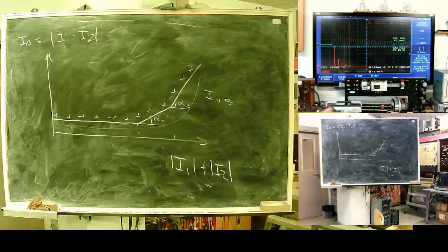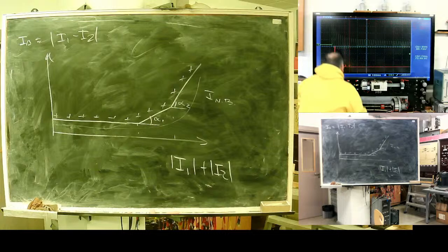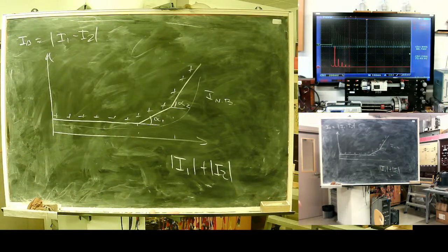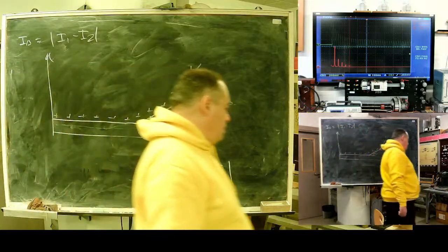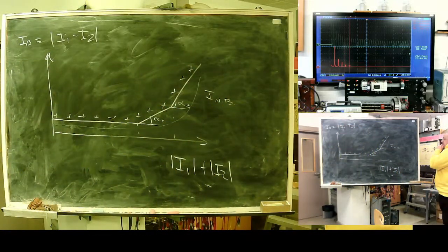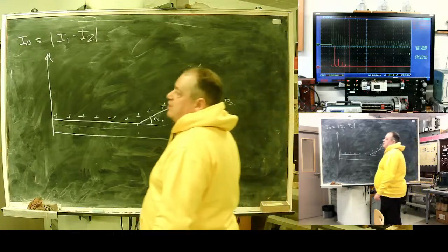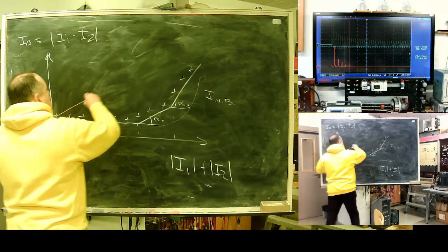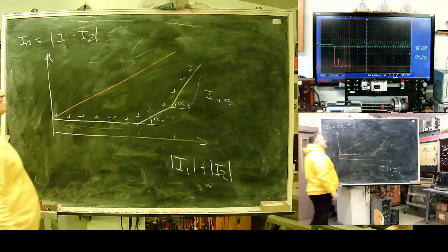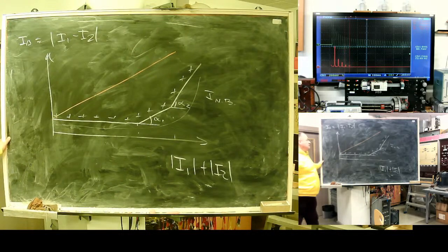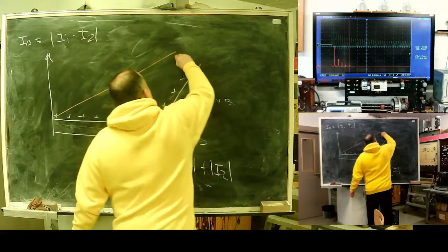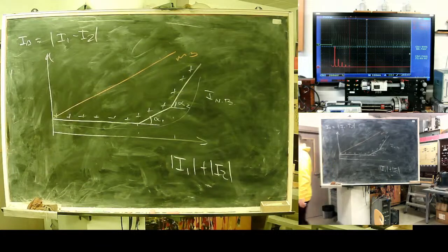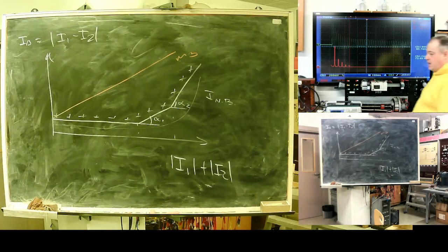See what we are looking at. Here is our Fourier decomposition. So the idea: you can use 150, or you can use a combination of 100 and 250, so the second and fifth harmonic. Such kind of protection has a restricted characteristic when, in the signal, we have high harmonic presence.